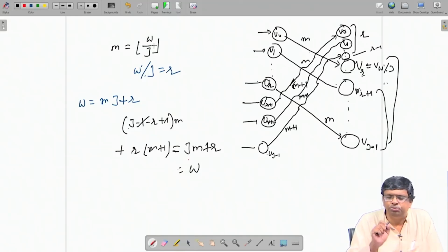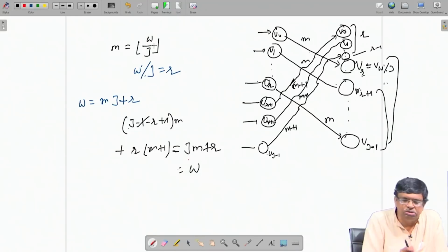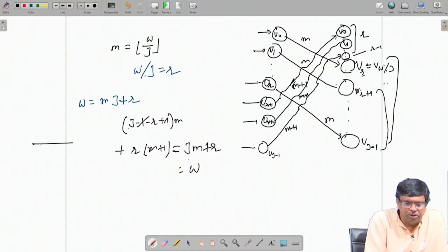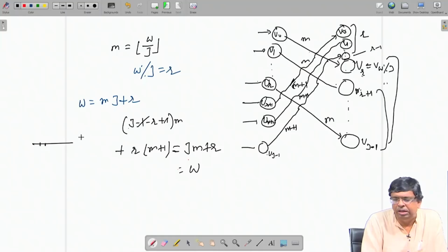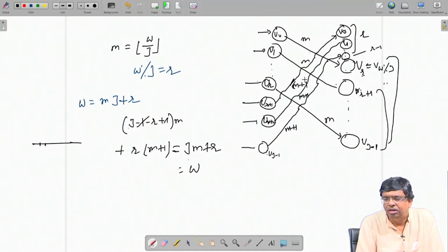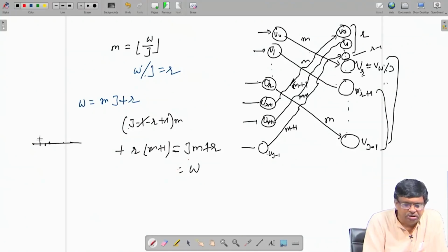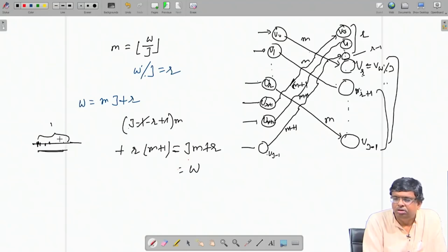But remember, w was with respect to the input clock, the original input cycle, which is faster. So, here that would have been one input cycle. So, this is faster. So, you take w of them, that many delays. But now, when I say m, it is with respect to the system cycle. System cycle means j number of input cycles. If you take j such, then this is one system cycle. This much is one system clock period, all right. So, in terms of time, it is the same.